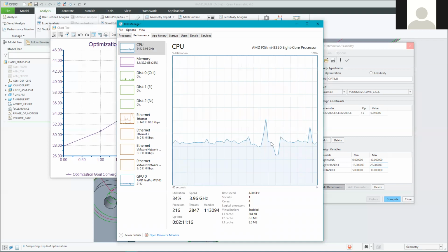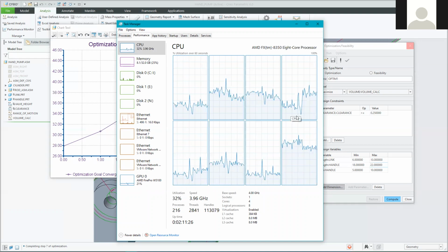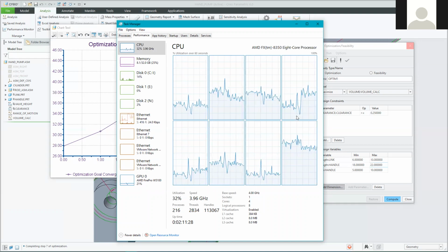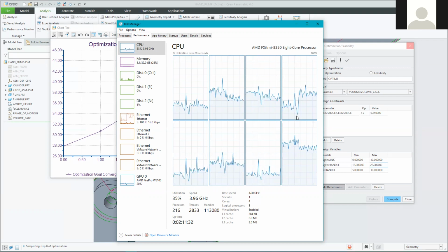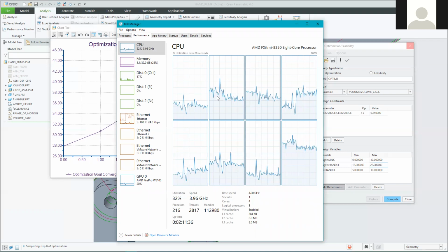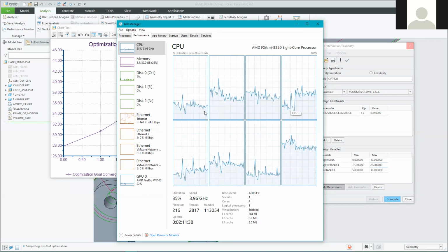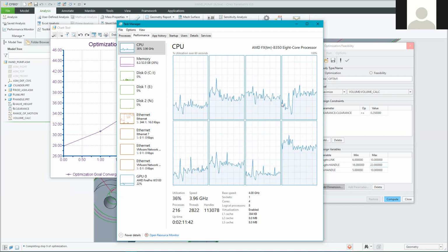So it's not terribly overloading the CPU. So I suspect I could probably drop back into my installation of Creo, and I think there's a parallel processing option that you can tick as you're installing it that is off by default. And I think that is possibly the issue at the moment. So it's not fully utilizing my multi-core CPU, which is why it's quite slow.